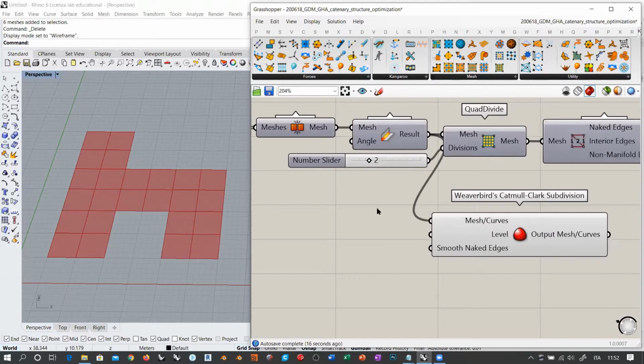How does this work? Well, it doesn't allow specifying the number of divisions that you want along the sides of your actual polygons. Okay, but it's, let's say, a loop, this kind of algorithm. So level is actually saying I take one quad and subdivide it once. Well, subdividing with a Catmull-Clark algorithm means that you get 4 polygons out of 1. So in the next iterations, you will get 4 polygons out of each polygon from the first iteration. So you don't have 3 by 3 quads. Okay, you will have eventually 8 by 8 quads, or sorry, 4 by 4 quads.